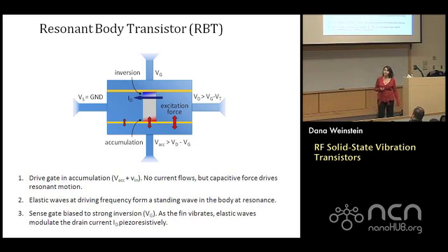So now it looks like a weirdly deformed split gate FinFET, right? Where my fin is actually some weird shape corresponding to my resonant cavity, where the length here defines the resonance frequency. So what can I do? I have two gates, and source and drain.